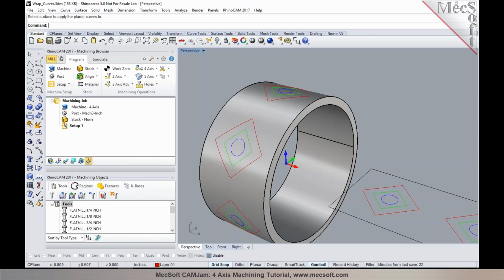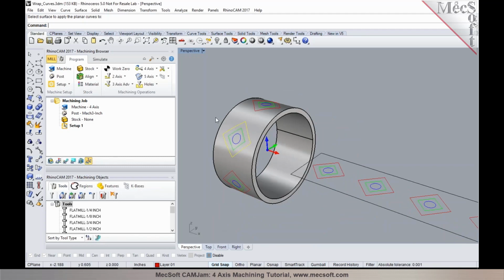So you would be able to directly select these curves as your part regions when you program your toolpaths inside of Rhino CAM or Visual CAM, or even Visual CAM for SOLIDWORKS. You can directly select those curved geometries as your part regions for programming these toolpaths. So I'm going to now show you an example of how this is being done in the CAM.